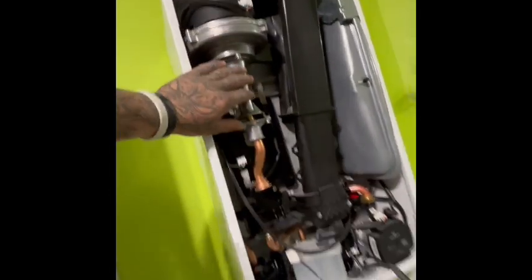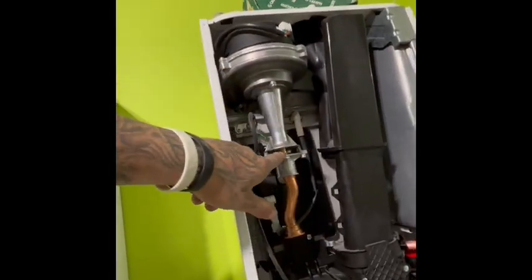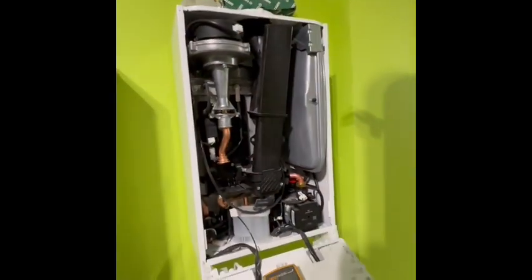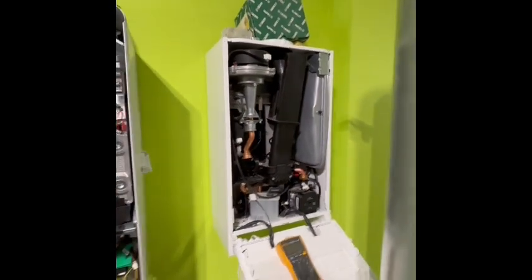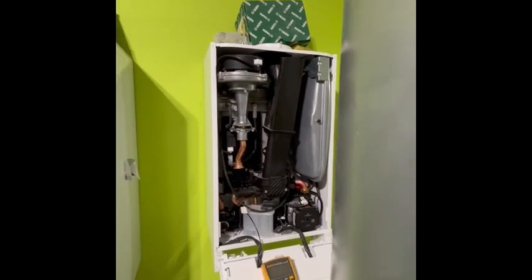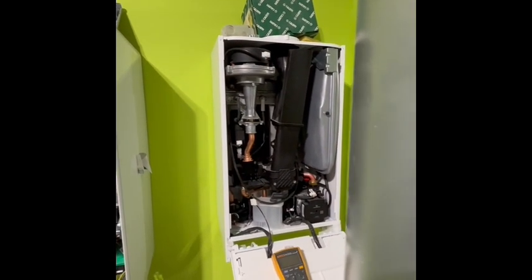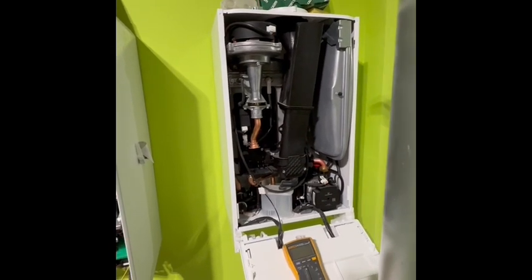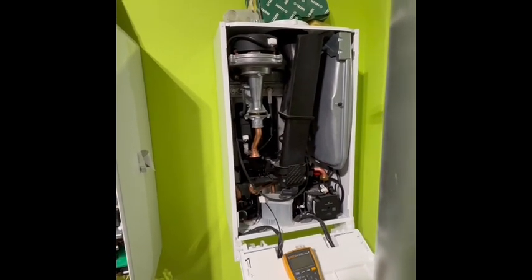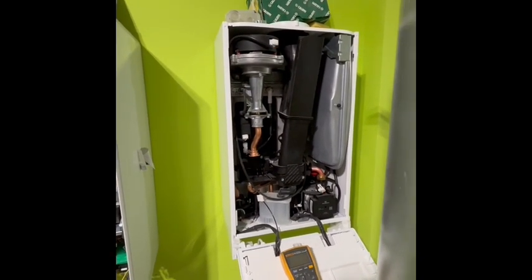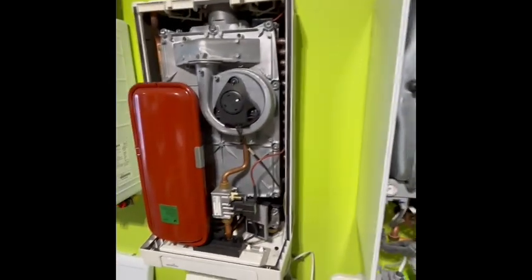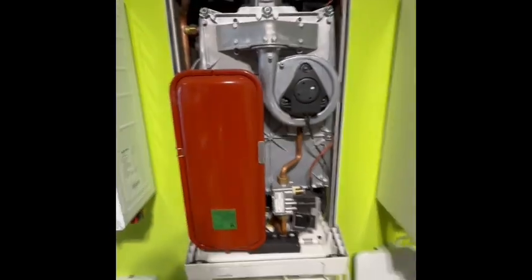Same on that boiler there, that's your venturi, there's your gas injector there. If you put your thumb over there and restrict the airflow, it'll cause the boiler to light sometimes if you're having issues with gas supply or air circulation faults. Then you know where you're looking, that you're on some sort of restriction somewhere, or the gas supply is being restricted. So every boiler is different, but the same process applies to every single boiler.